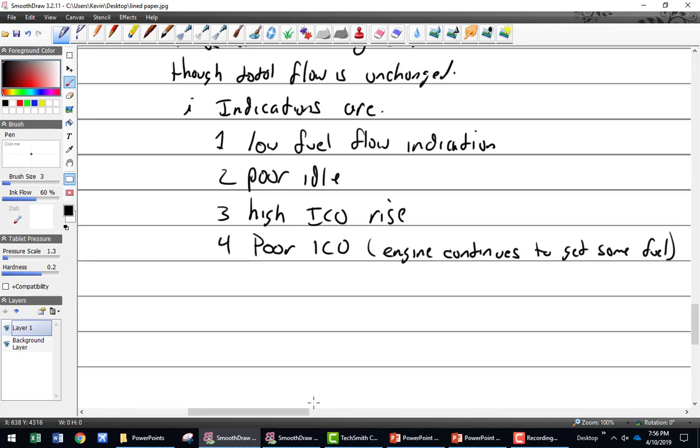A V slot, and that is going to be doing the regulating before we get to full throttle. But once we get to wide open, the V slot opens all the way up. It's no longer any sort of restriction. In the flow divider, the next restriction is the injector nozzles, where they're designed to operate at wide open throttle. And so the higher the pressure goes, the more flow we're going to get through the injector nozzles. And that's the way it's supposed to work.